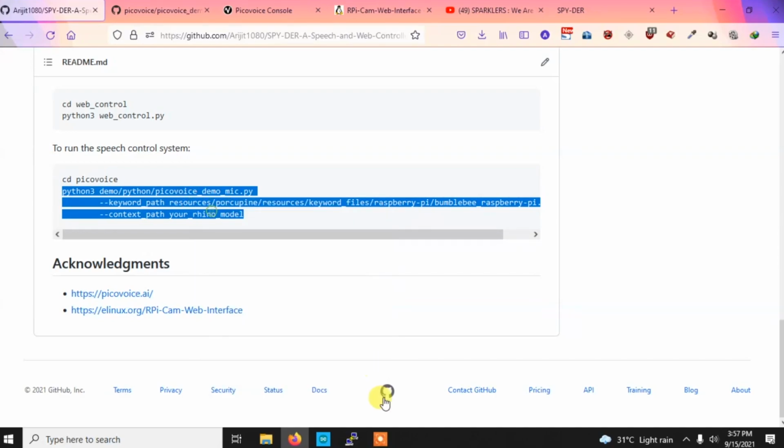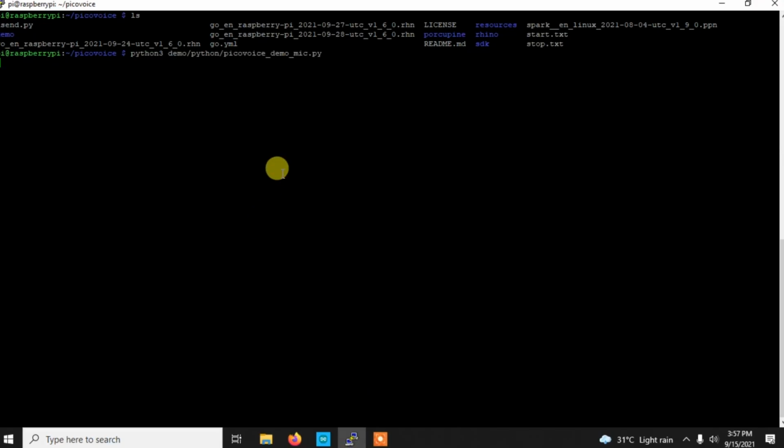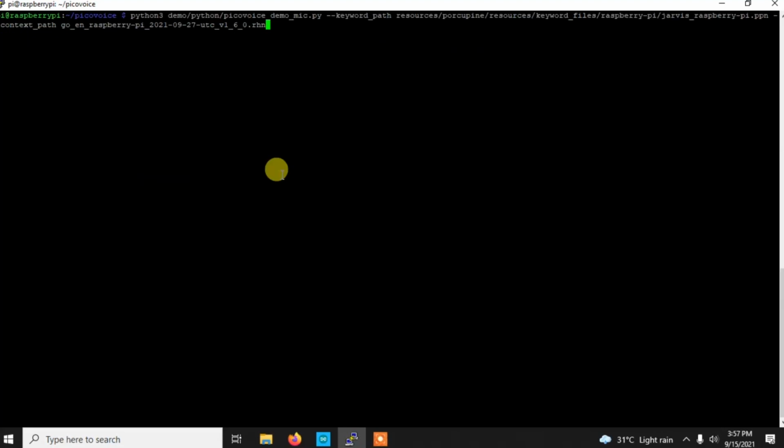So the only thing I need to change in this query is, okay, sorry. As you can see here, I have the command python3 and the name of the file is picovoice_demo_mic.py. Then in the keyword part I have this. Here I have the Jarvis one, so let me change it and let me show you. Here, as you can see, it is written as Raspberry Pi Jarvis Raspberry Pi.ppn.